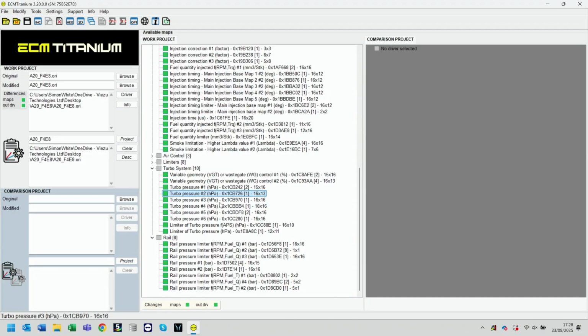No, I mean that's a great point, and this is one of the ways that you'll see sometimes a good map versus a poor map. A good diesel map shouldn't have any negative impact on the diesel particulate filter at all. Whereas a poor map may have changed all of the turbo pressure maps and the car goes great down the road, but has now subsequently stopped doing the regenerations because there's too much pressure through there and you have DPF faults.